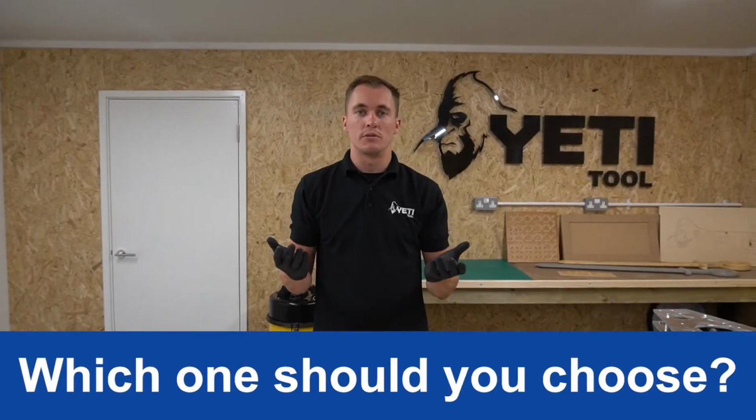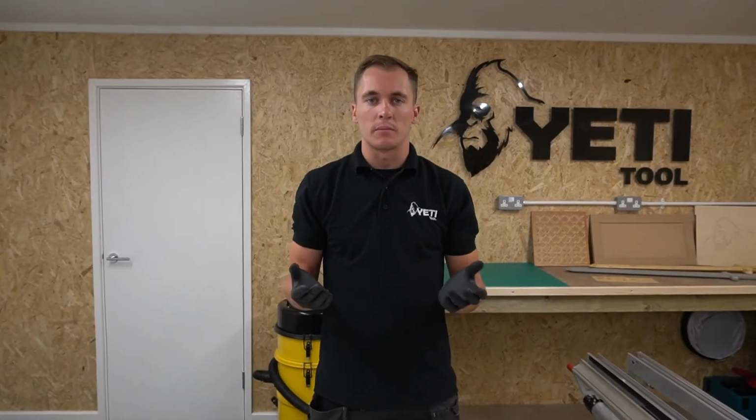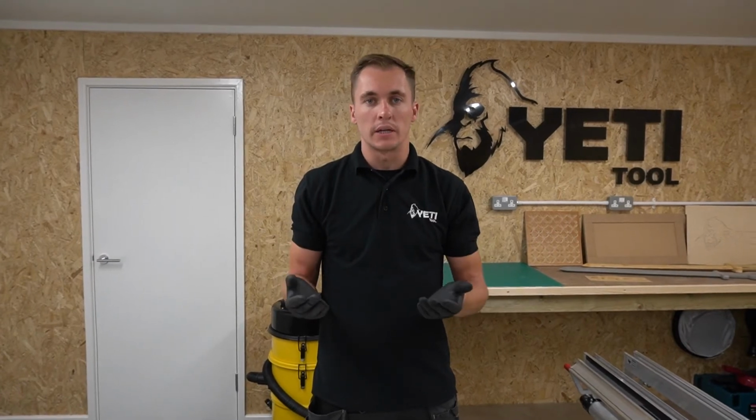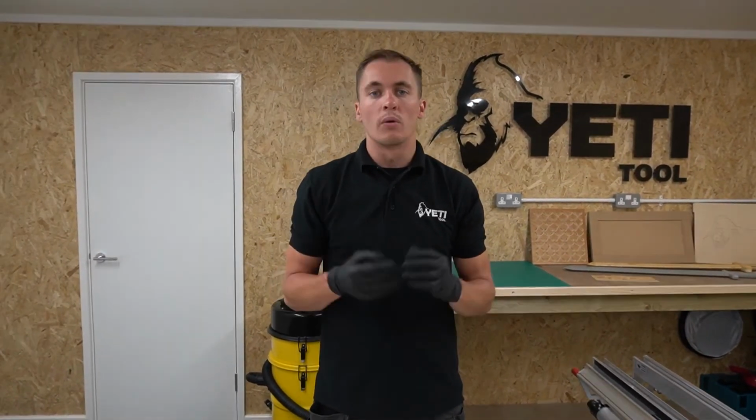Which one should you choose? Climb milling uses less power to move the cutter through the material, so we'd recommend using climb milling on SmartBench where possible. You may have some scenarios where you need to use conventional milling, such as improving accuracy or cutting certain materials. All of the values in our tables are created using climb milling approach. If you need to use conventional milling, then you can do so, but we'd recommend you reduce your feed rate by around 30% to begin with.